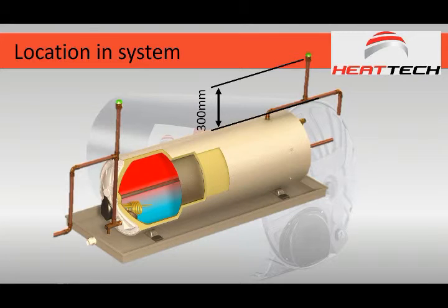My question was regarding the pressure rating of vacuum breakers. I'm not aware of vacuum breakers that are rated for a minimum pressure, let's say 400 kPa, that cannot be used in a 600 kPa system, for example. I would have thought that because they are units that are not responsible for regulating or relieving any kind of pressure, like a TP or a PRV, that their positive pressure rating would be a threshold predetermined.